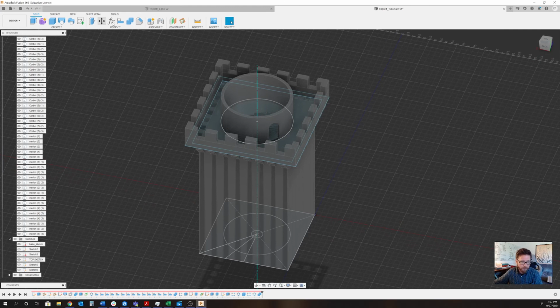We've covered quite a lot. We've covered aligning. We've used a few different tools, including the Loft, the Combine tool. We've created lots of new construction planes. We've created a new axis, lots of stuff to talk about. And of course, the last thing to do is to give yourself a little bit of information when you hit save. And I'm just going to say finished parapet. And that's the last thing that I did. Okay, so that's it. Looking forward to seeing you all soon.